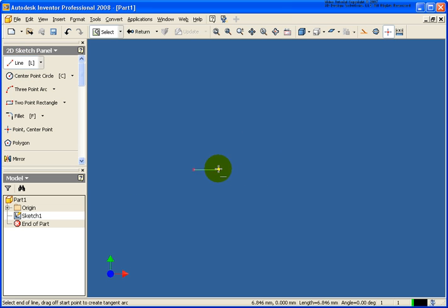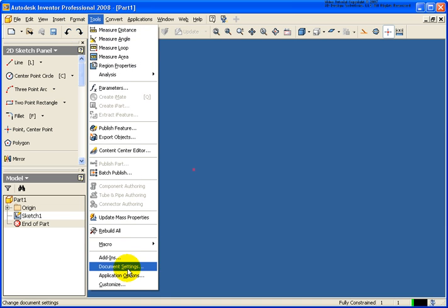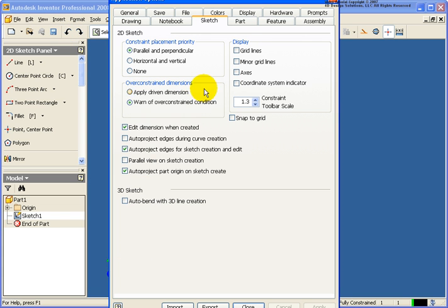So as I'm going to draw my first line, I get the horizontal line showing me that it's a horizontal constraint. As I draw that second line going back up, you'll notice that I have a perpendicular constraint and another parallel constraint, and I'm getting another parallel constraint that you can see on that right side. So let me undo those real quick,